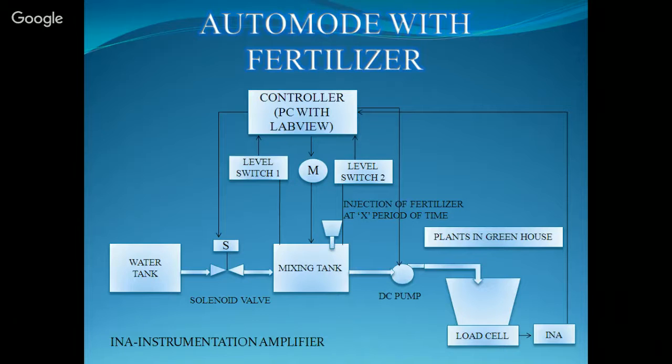As mentioned earlier, load cell is used for measuring the moisture content of the soil in the potted plant. The output voltage from the load cell and instrumentation amplifier circuit is acquired with the help of myRIO. The pot with dry soil will be of lesser weight and the one with sufficient moisture content will be of more weight.